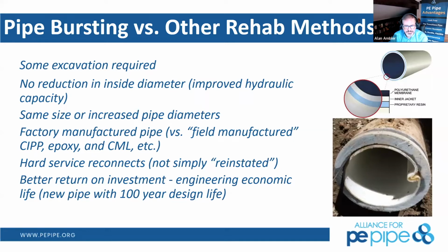So what you're seeing here is field made pipes that have lips or other problems within that cured in place pipe liner. And the only way to be able to rectify this is to excavate and cut that section out. So your crew has to be fairly attentive to successfully install a pressurized cured in place pipe liner here, comparatively to gravity sewer, which has a lot longer history in CIPP.